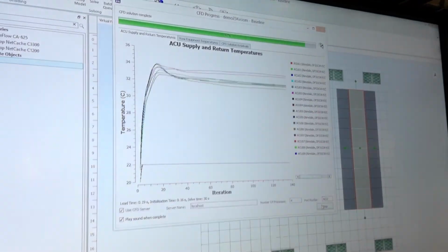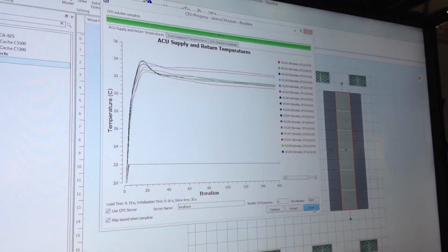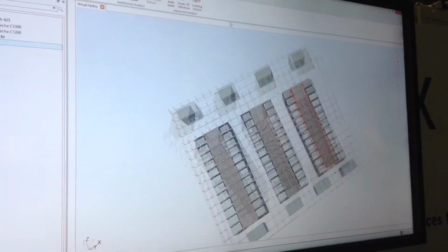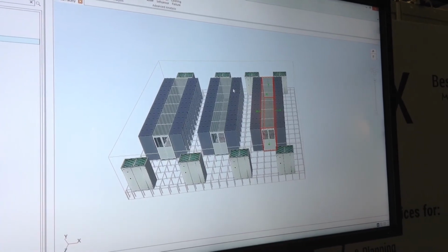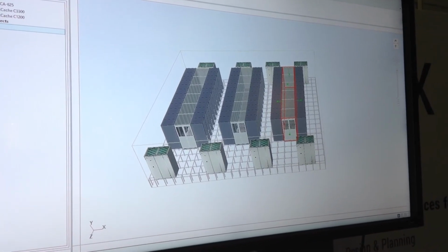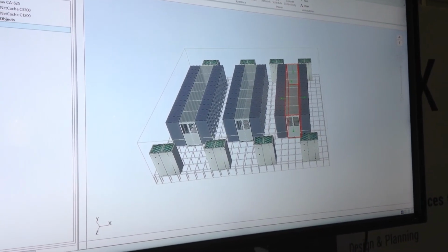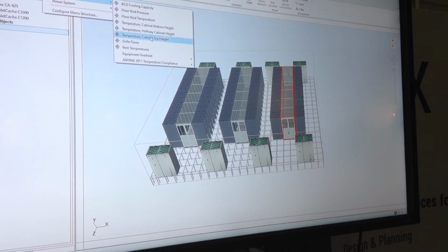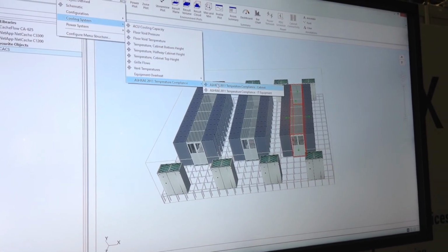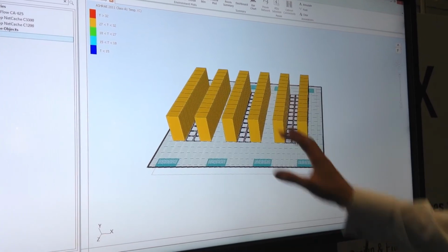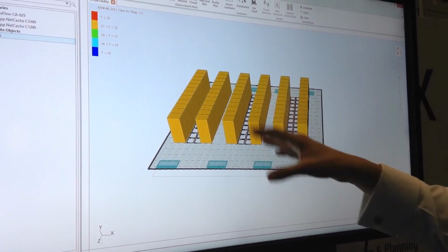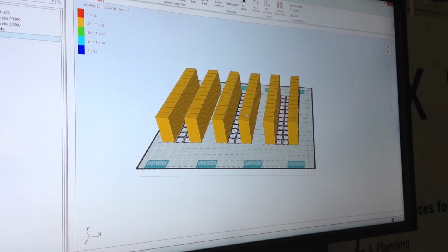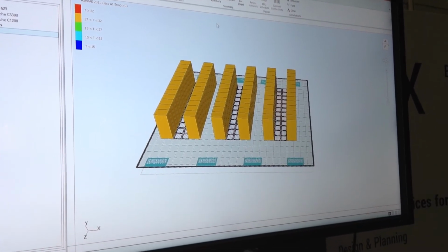So we can see we've pretty much finished solving these results. Now I can start looking at some results within my space. We have traditional CFD results, but we've also got results focused specifically on the data center. So I can look at my ASHRAE conditions, and whether my cabinets are sitting within ASHRAE recommendation, and actually they are on the warm side, but they're in allowable range, but maybe we need to do a better job of our cooling.